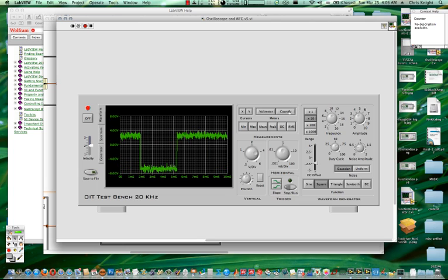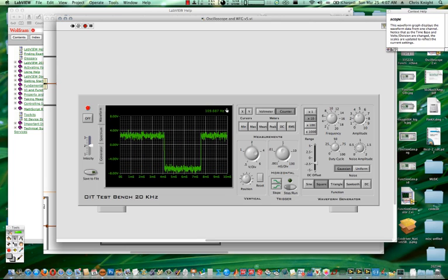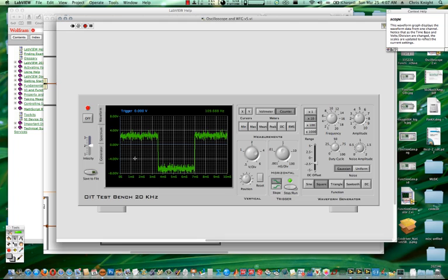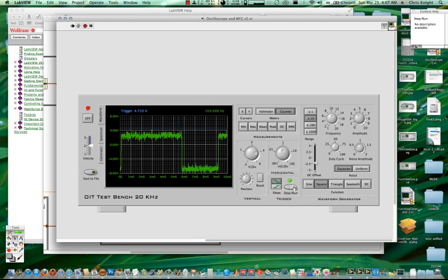First, we're going to turn on this button, which is a frequency counter. It shows up on the top right-hand side here. When we turn on triggering, we can set that triggering by dragging this cursor. So we'll set it right here, kind of at the top of that noise. Well, I guess it's too close to that noise. And it triggered again on some more noise.